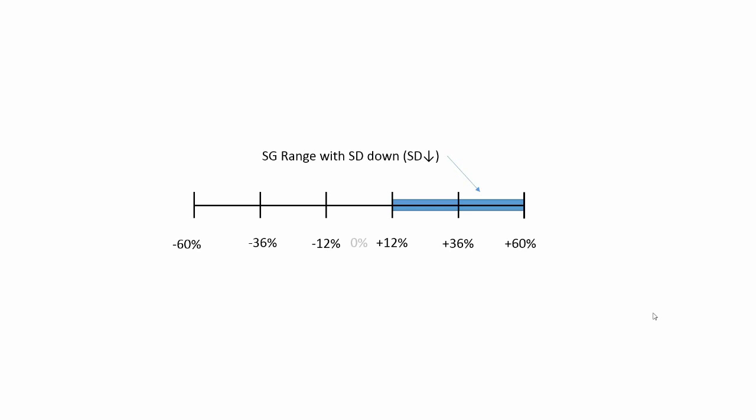The way we will do this, or the difference between the two ranges, is this range is 72 added on to the previous range. The position that gave us minus 60 originally, we want to give us plus 12. The difference between the two is 72. So let's go on to the Taranis and do this programming.